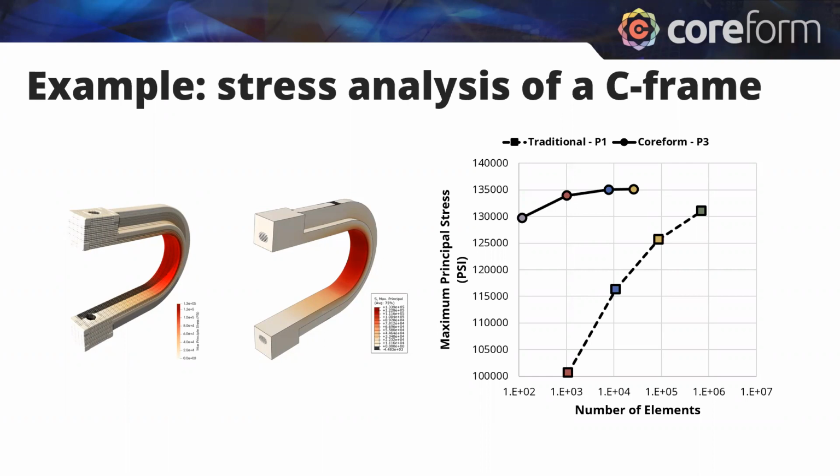When our documentation, or theory manuals, have been published, you can read about that there. That's what allows us to get away with many times fewer elements. But you still need to predict the weights. And to do that, you have to have an accurate integration, at least at the start, to be able to predict quadrature weights.